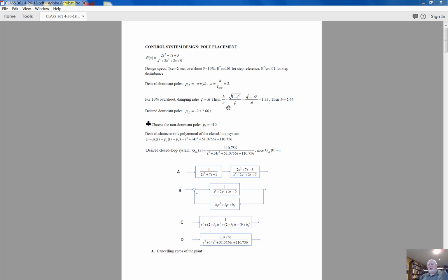Take a second order system, the classical, canonical definition of the second order system. Take the poles. The poles will be 2 complex conjugates, and get the relationship between the imaginary part and the absolute value of the real part. You will get exactly this result.